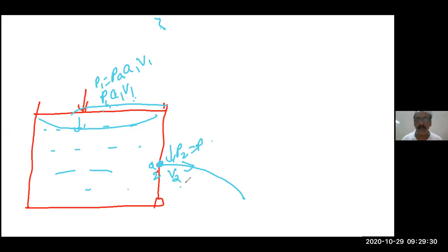Yes, sir. But you can see here water splashes very fast, but here that layer comes down very slowly, isn't it? Suppose the dam has a very big reservoir. On one side of the wall there is a small hole. There you can see water splashes at very high velocity. But will the water level of the dam come down fast? No, it goes down very little. So we can say V1 is very, very smaller than V2.